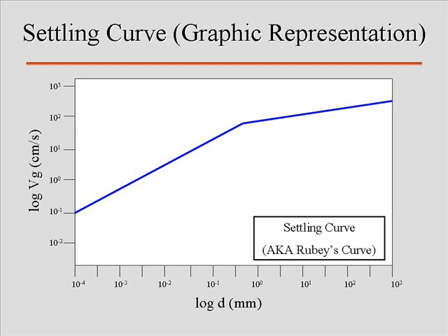I'm aware that many of you were working with Dr. Connors in terms of doing some grain size analysis last year. Did you use the hydrometer and sieve method? Yes, sir. You're not using that method here. You're using the pipette and sieve method. What's similar about those two? Two-part components. The thing you were doing last time, the hydrometer dealt with the laminar flow area, the fine grain size. The sieving dealt with this. For our method, we're using the pipette to deal with this, and the sieving still uses that.